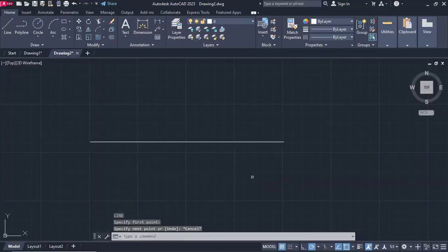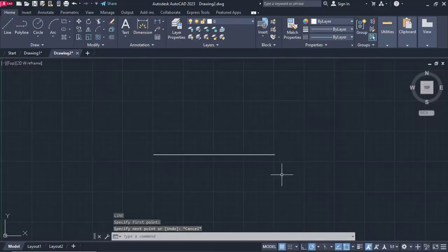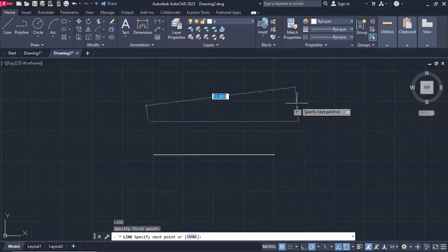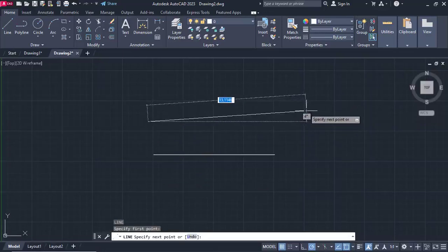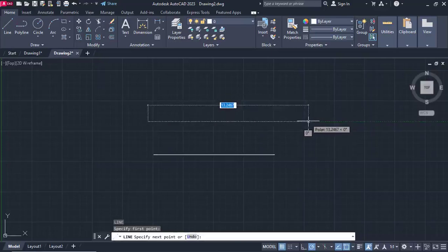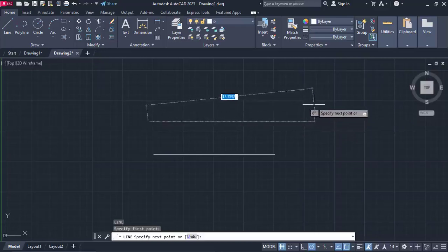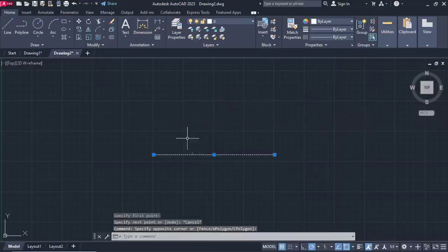Mr. Prince, let me just say something, please. The little I've come to realize here is that once you pick the first point after picking your line tool, you have to key in the length of the line before picking the second point. Entering the length after the first point will just give you an accurate 10, even without adding whether it's in cm or in mm.